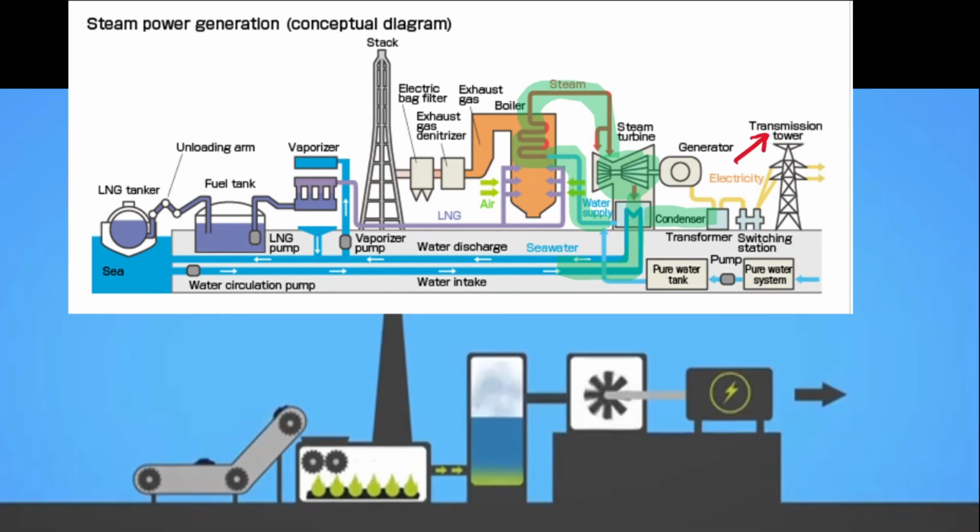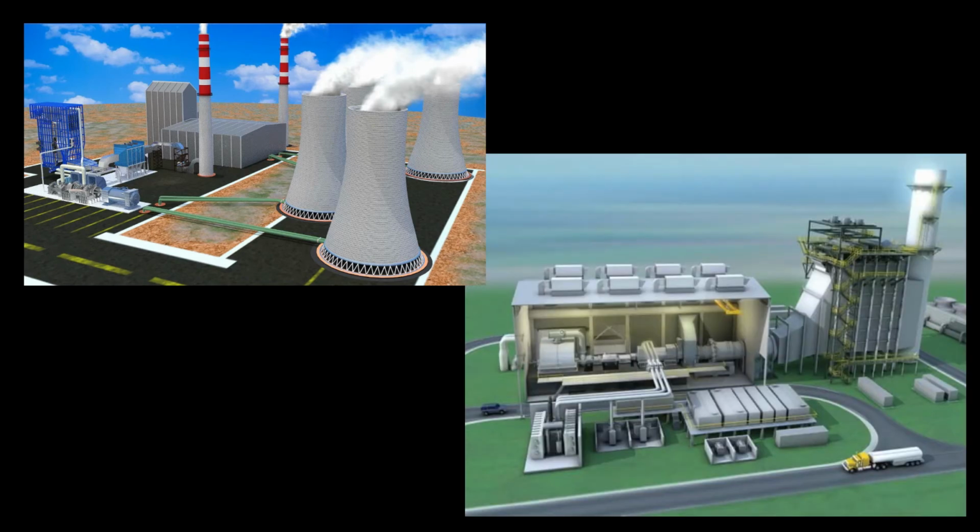The greatest variation in the design of thermal power stations is because of the different heat sources, including coal, natural gas, waste, or petroleum. Thermal power plants are designed on a large scale for continuous operations and base loading. The majority of plants use 1 or 2 units of 400 to 600 megawatts.